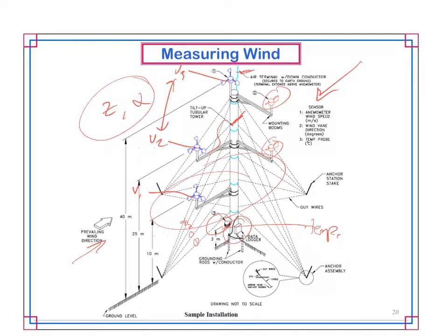It actually has more to do with data checking. What if you have, so this records the data every 10 minutes, and there's a lot of data. It's a tremendous amount of statistical analysis to make sure that it's correct. So if you have a bunch of data that says 0 meters per second, but the wind direction has been changing, so it should be indicating movement, but there's not been any for speed, and the temperature is below 32 degrees, or 0 degrees Celsius. These things are constantly spinning. If they get ice on them, they could lock up. So it's really just for data checking.